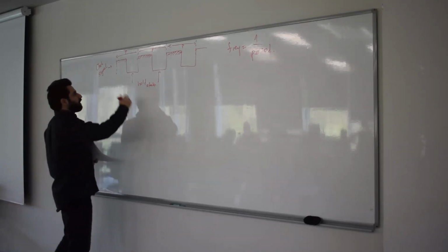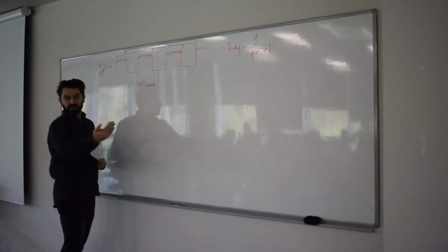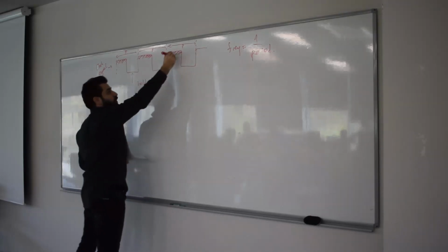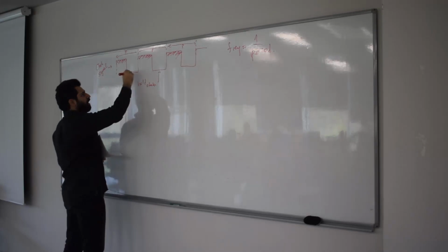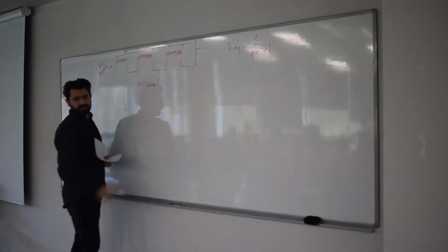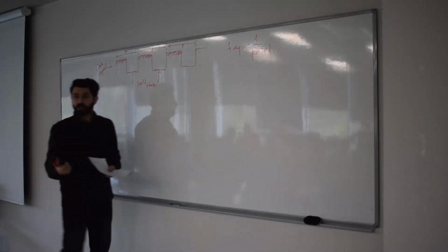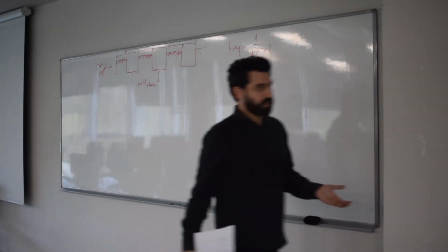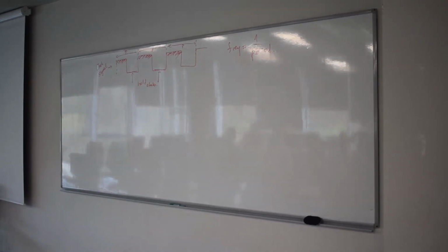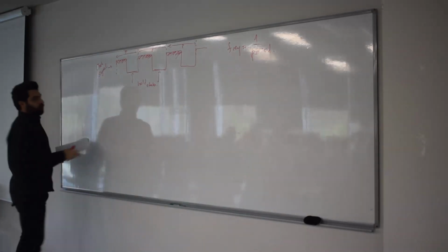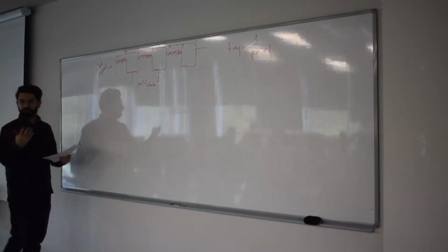So now, for the latch, we have these hold states. These are changing states where D is copied to the output. How about these? These are the hold states. As you can guess, the clock is going to be connected to the enable. This enable will be connected to the clock signal. All right. Now, coming back to our flip-flops.